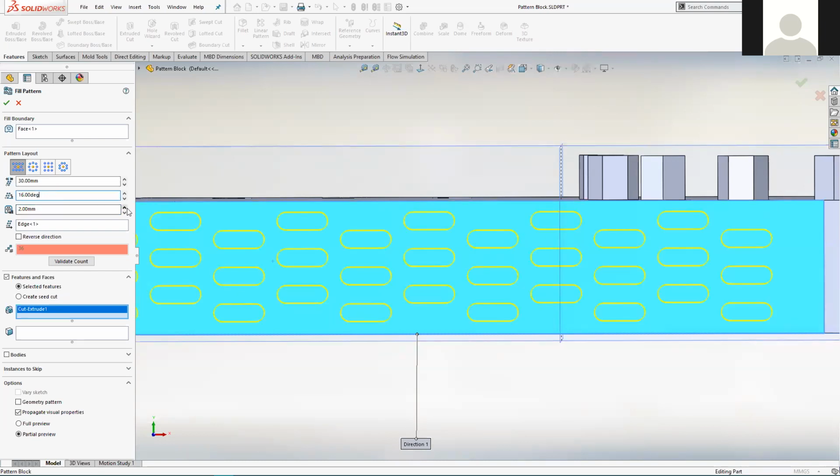So I'm just going to bump this value up. There you go. So if we put, let's say, 8 millimeters in there, it wipes out the copies that were near to the margins. It's also got the one over here. So I think there was another copy there. And because that was too close to that margin, it's got rid of that one as well.